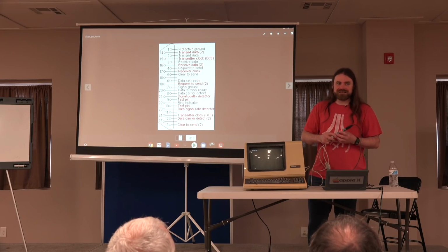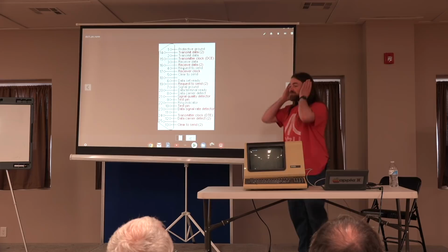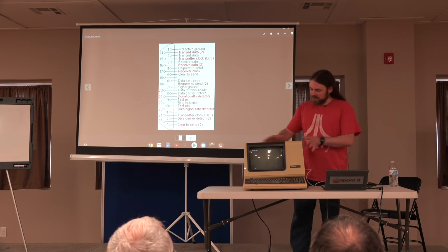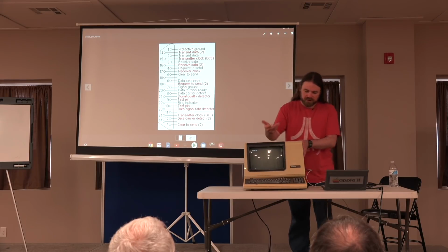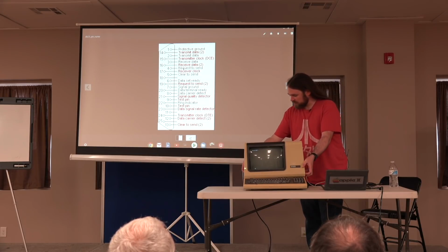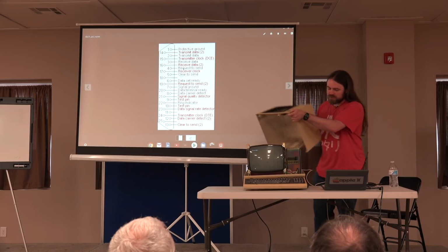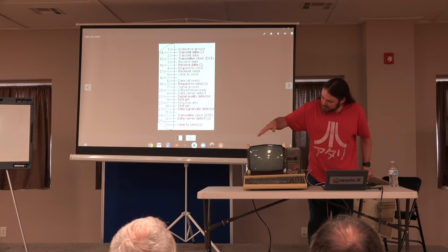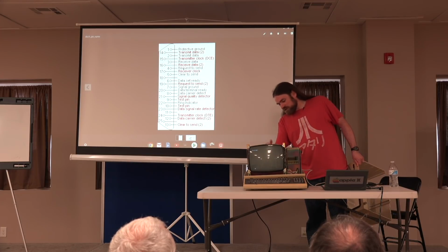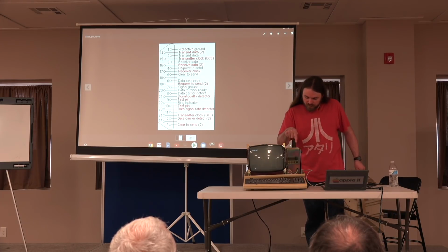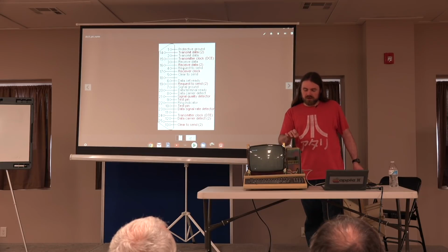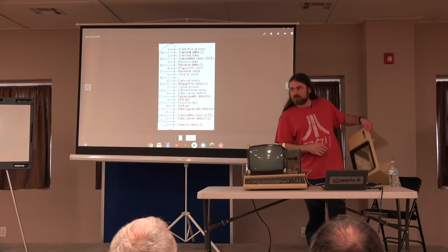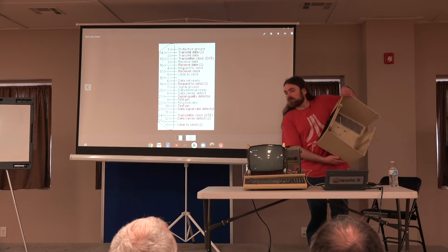Oh, of course, yes. So I guess one thing I should mention with terminals is that they're all very, very different. A terminal in its basic form is just a keyboard, a monitor, the electronics to do all of that. In fact, this one, I'll take the cover off. There's not a whole lot in here. Yeah, it's a black and white monitor. There's the high voltage and the electronics back here, and then you've got one board of logic. This one is microprocessor controlled. I think it's an Intel 8080 in this one. Some were Z80 controlled. I think it's an 8085, but it might be.